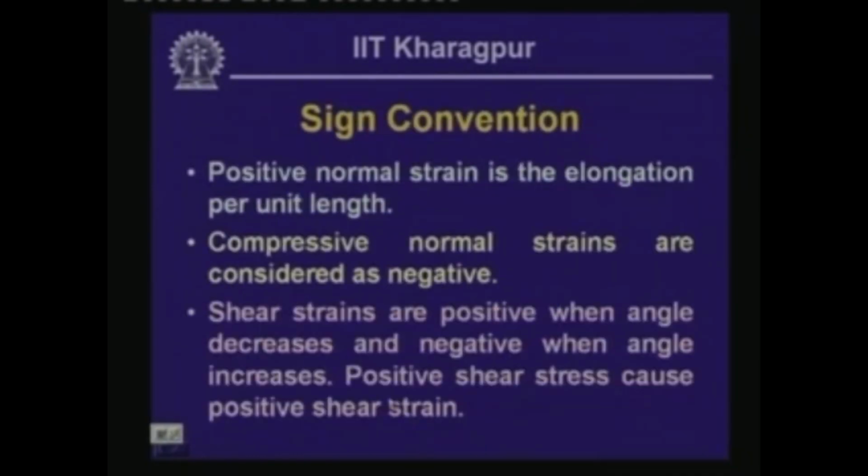Well, now that we have evaluated the strain at a point if the reference axis is oriented at an angle of theta with reference to the rectangular axis system x and y, we have seen how to compute the value of the maximum normal strain, which we have called the principal strain. We have seen how to compute the value of the maximum shearing strain and the orientations of the principal strain and the shearing strain through the angles theta p and theta s.